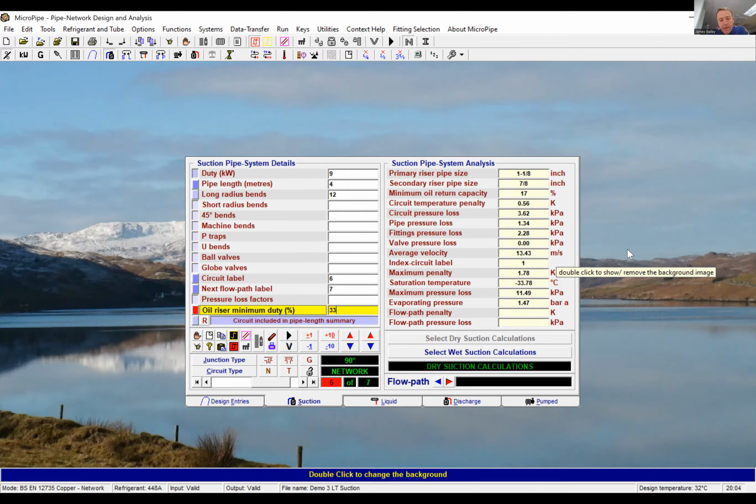Yes, I do. And what I can say, Trevor, is the difficulty here is when pipe work's hidden from view, especially in the UK, technicians at night time are going to look and think, these are experienced people, but they won't necessarily think, well, I can just put 1 vertical line in here and it's going to get the oil back. But what they're not necessarily appreciating is this, when we're talking specifically about oil return, because I'm looking at getting it back throughout all seasons.